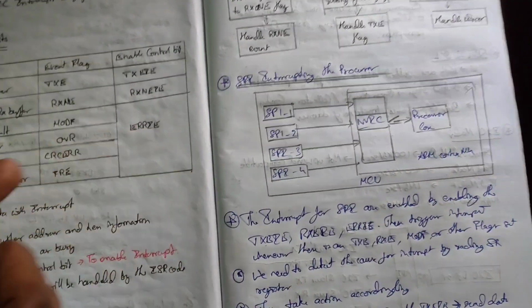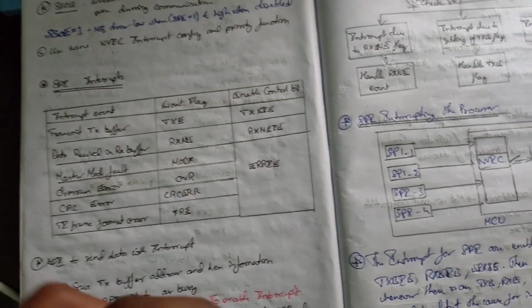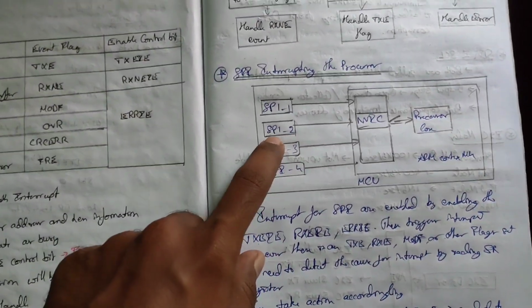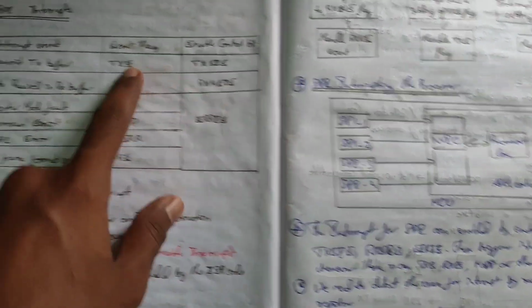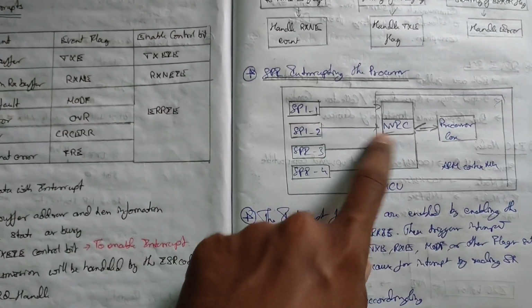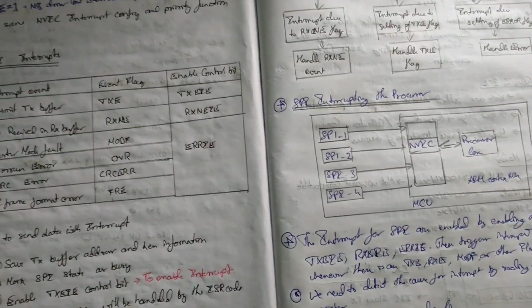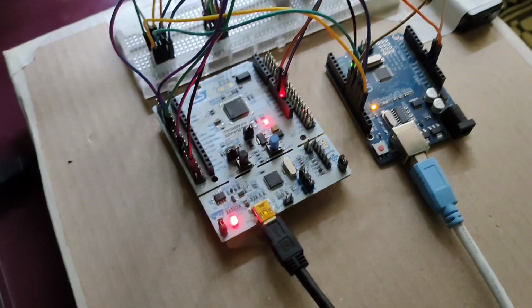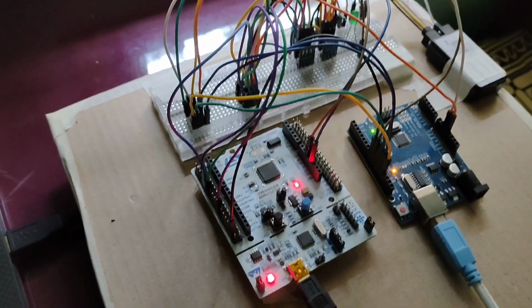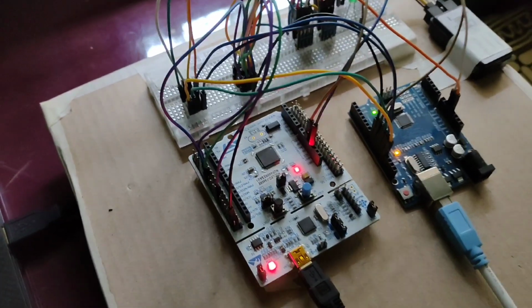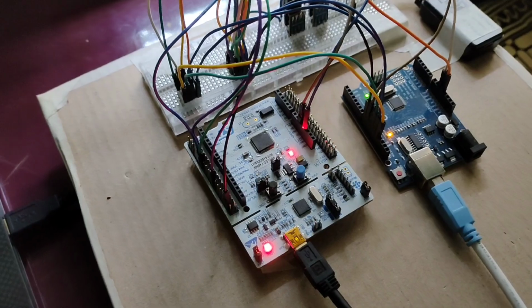So to find out which triggered the interrupt, we need to look into the SR status register of SPI, then decide which of these flags triggered the SPI interrupt. Whenever there is a buffer to send from Arduino to STM, we'll be using another GPIO interrupt.